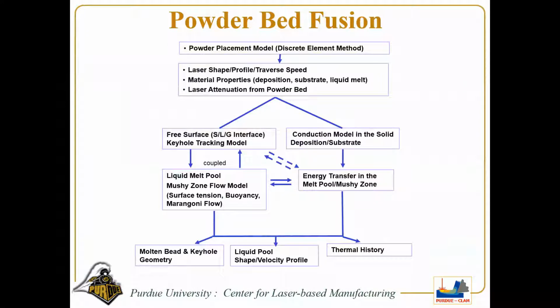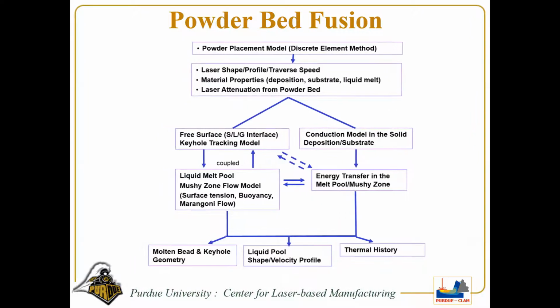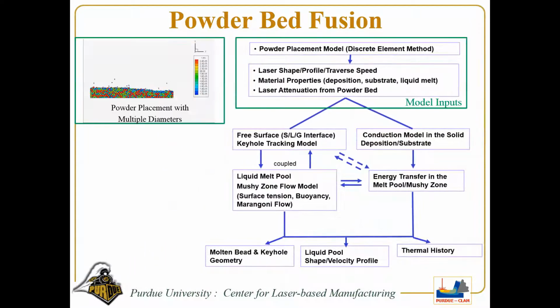And you do the same thing for the powder bed one, and we use something called the discrete element method to study how the particles flow in the bed. The rest of that one is very similar to this one. The particles will drop on the surface there, and you see how we simulate the motions of each individual particle. After things get settled, we'll have a layer of particles deposited on the bed, and then you will start doing a simulation of this one.